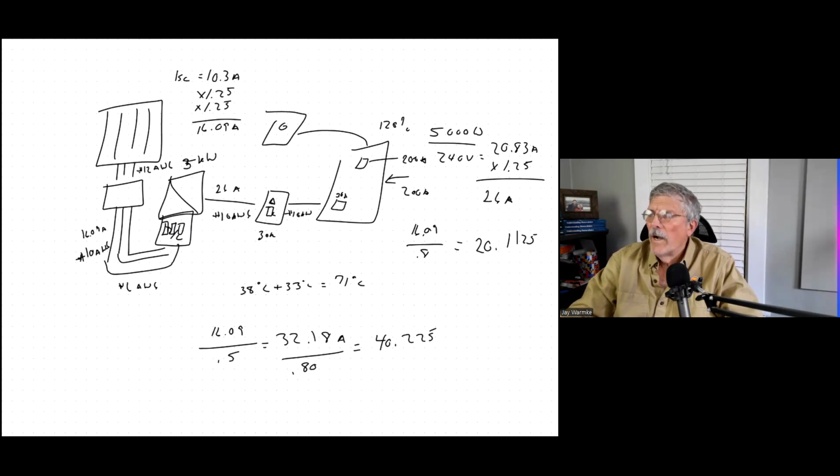Like when you're sizing the wire, the first thing you've got to remember is the 1.25 safety margin. And then before you get to your first electronic device, you've got a second 1.25 solar variability margin. Then you've got to worry about temperature corrections, conduit fill corrections, things like that. And the rest of it is mostly just looking things up in tables. And then of course the 120% rule, which everybody runs afoul of when you get to the service panel. So any questions about that?